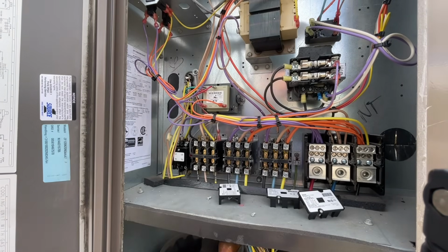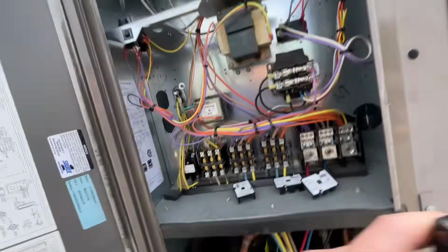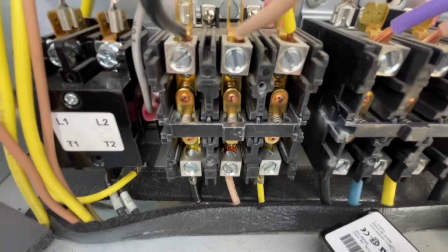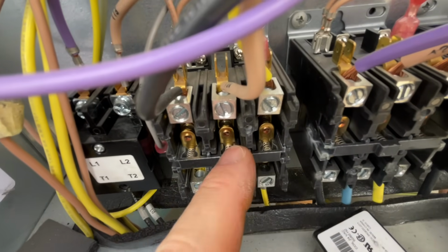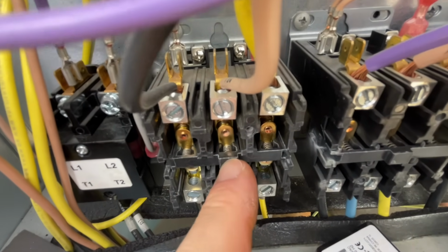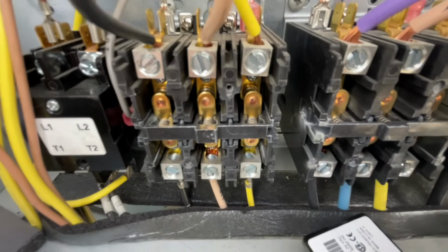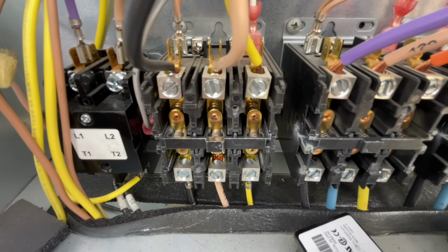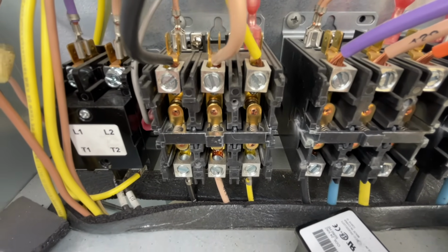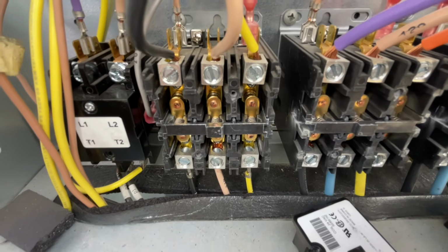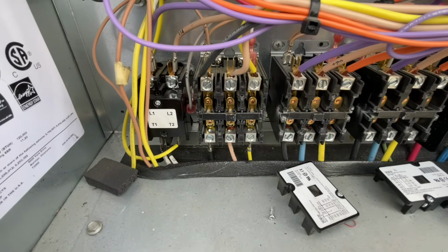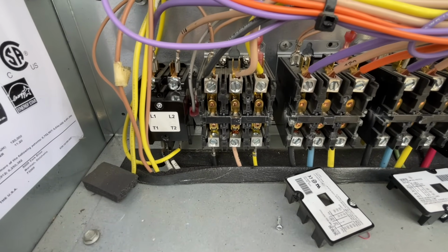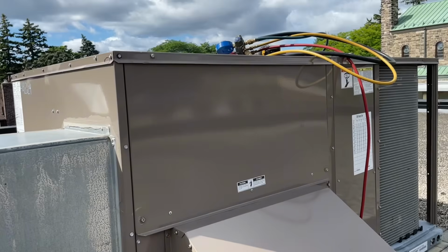Those also look okay. So this is something you guys should do if you're ever doing maintenance or you have a breakdown, but you see how those in here, where these energize, they look nice and shiny. That's what you're gonna wanna see on your contactors. If you've got any burn ups, burn marks, carbon tracking, you're gonna wanna replace those. It'll save the loads they provide.